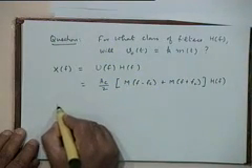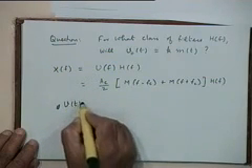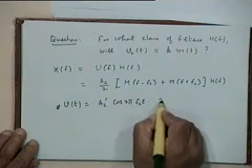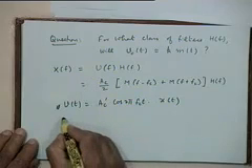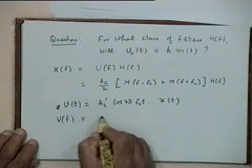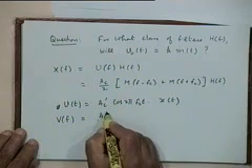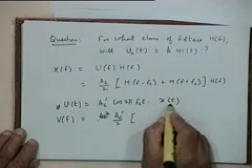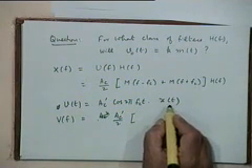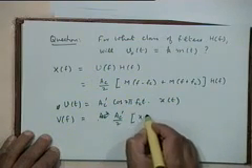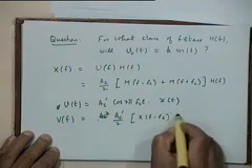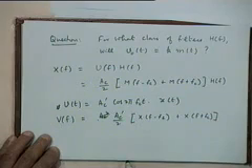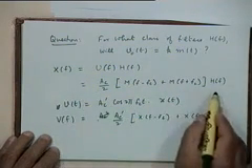If I define v(t) as A_c prime cosine 2 pi f_c t times x(t), then V(f) will be A_c prime by 2 into the translation of the spectrum of x(t), so X(f minus f_c) plus X(f plus f_c). But X(f) is given here, so can I substitute that?